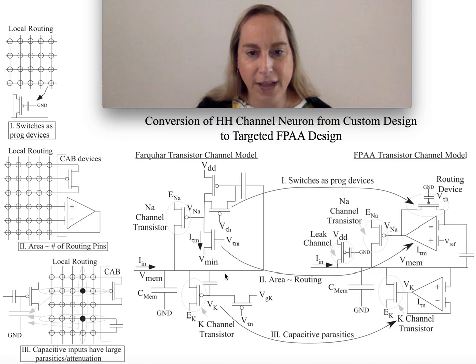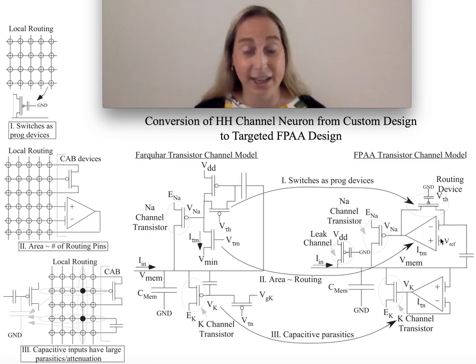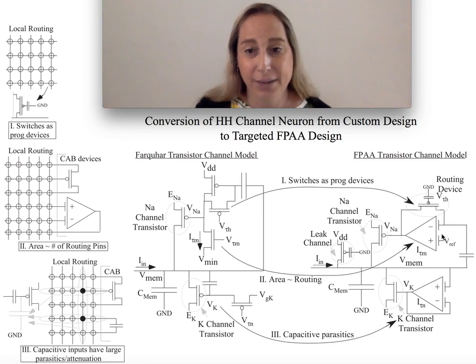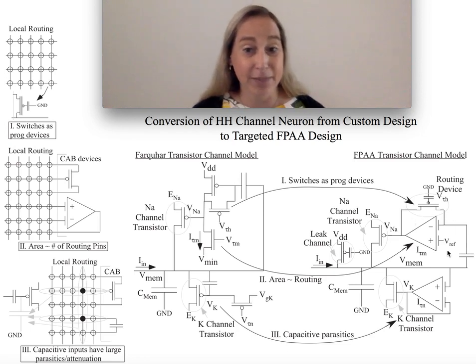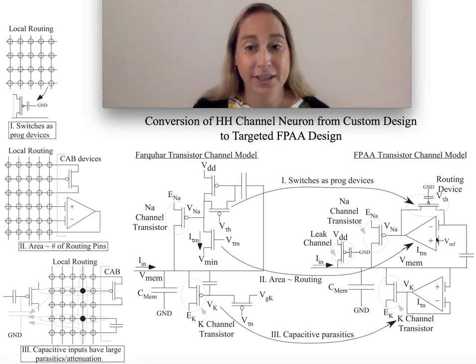So what happens is this high-pass filter turns out to be, I flip the PFET to an NFET and make it a low-pass filter. I use the floating gate OTAs to help me set the biasing infrastructure. I use another floating gate OTA to help me set its biasing structure. I don't need a lot of gain out of it, so it's not really an issue. It runs near open loop anyway, and that matches the dynamics fairly well. It also still gives me other OTAs in even that CAB to build other structures. So you get a circuit that is efficiently built in the medium you're working with and keeps the dynamics that you would want to work with.